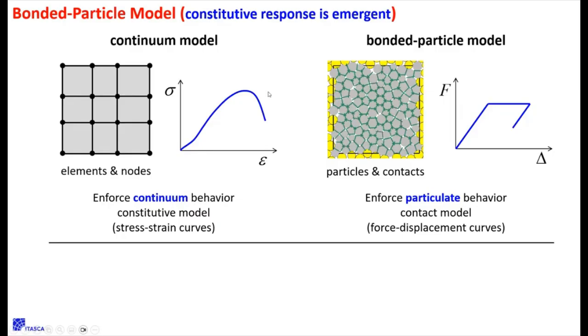Just like here it's stress strain at each element, and each one tracks its own thing, here each contact tracks its own place on this curve. This is my simplest possible nonlinear curve. This is not brittle; this is actually a granular system. Remember, shear force goes up, slides, unloads, right? We could show a parallel bond curve, which would be a bonded system, but you get the idea.